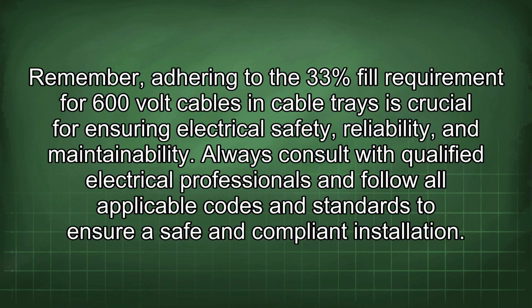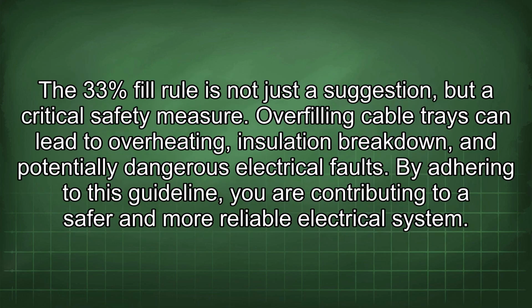Remember, adhering to the 33% fill requirement for 600-volt cables and cable trays is crucial for ensuring electrical safety, reliability, and maintainability. Always consult with qualified electrical professionals and follow all applicable codes and standards to ensure a safe and compliant installation. The 33% fill rule is not just a suggestion, but a critical safety measure. Overfilling cable trays can lead to overheating, insulation breakdown, and potentially dangerous electrical faults. By adhering to this guideline, you are contributing to a safer and more reliable electrical system.